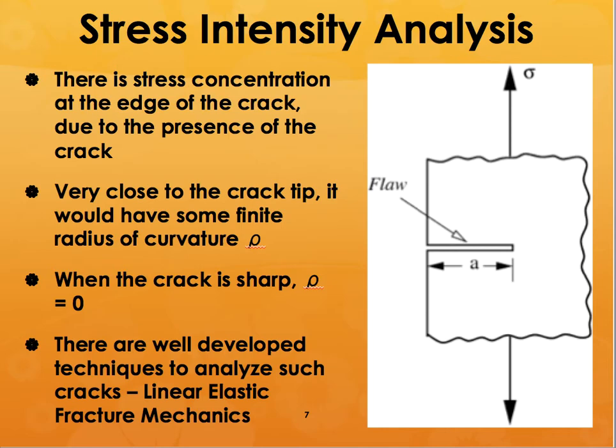If you have a flaw at the edge of the crack, there is a stress concentration. We know that there is a stress concentration at the edge of the crack, and you can assume that very close to the crack tip it has a finite radius of curvature.